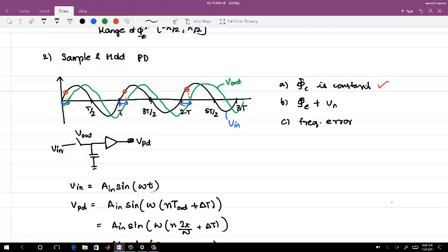Yeah, V out just controls the switch. You could say I was using a multiplier, where you would have current sources if you are using a CML based multiplier, which is more complex, right? Here this is simple. If my clock waveform is a square, I just need to sample it. So this is one of the very simple phase error detectors and quite energy efficient in many cases.